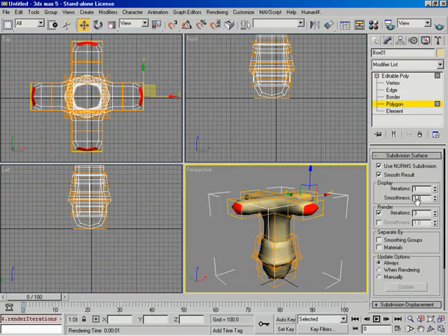All right, what smoothness will do basically is the subdivision surface, or NURMS, is going to look at all of the corners, where all these edges come together. And it's going to look at the actual angle, and then based on the setting that we apply for smoothness, it's going to determine if additional polygons need to be added in to smooth it out.